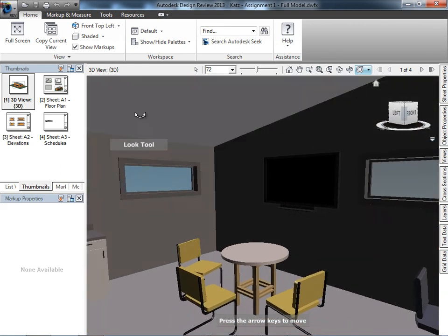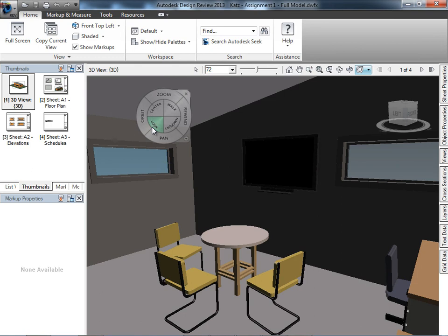And this is sort of a really cool way to share models, because people can share your model without actually needing the Revit software. All these different model objects actually contain the true information. So I know what kind of chair it is, I know what the data is behind that flat screen TV, I know what the data is behind this. So you can find that the DWF model is where we can change things, for example with Navisworks, or with quantity takeoff. It's a way of passing model information as opposed to just using lines. Okay, so what you're going to do is save out a DWF file that includes your sheets as well as that 3D view, and don't forget to submit that.